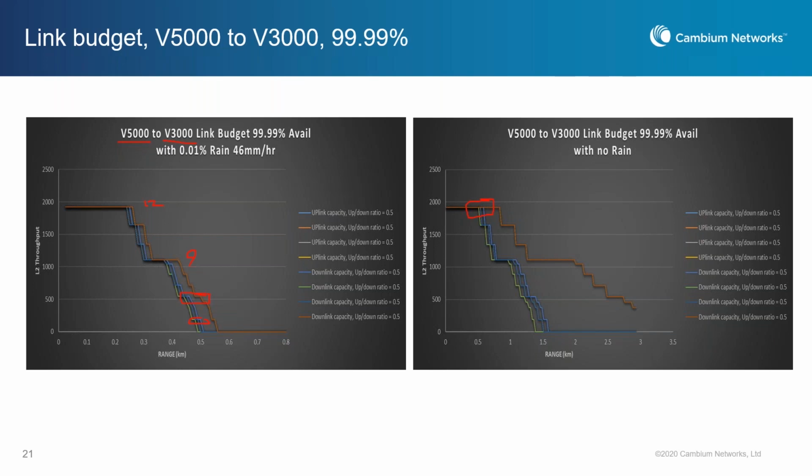But if you haven't lost the link, say you're just a little bit twisted, off by a little bit but the radio still makes the connection, it finds it's not on the optimized configuration, and every 4 hours it will do a realign, and you will not see any link drop. During the realign, it will remember the best direction to reach the best performance. So periodically, in operation or if you lose the link, the beamformer keeps tracking the right direction to beam.